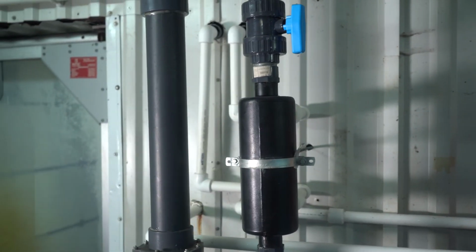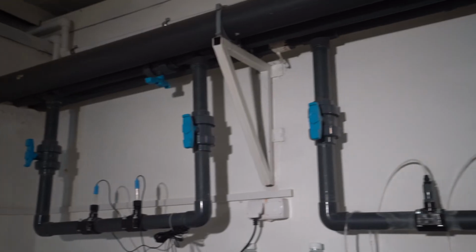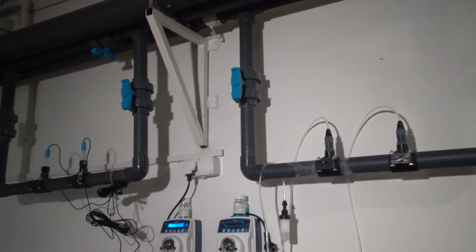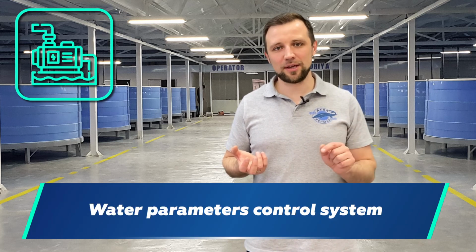I still prefer to heat the water in RAS in the automatic mode, to use an automatic pH regulation system, which doses the reagent, acid or alkali, when water parameters deviate from the norm. Also automatic feeders. You can of course feed your fish manually or automatically, it's up to you to choose. There is also a water parameter monitoring system, which allows you to automatically monitor and control oxygen, pH, carbon dioxide levels, redox and several other parameters in RAS and gives an alarm signal if something goes wrong.